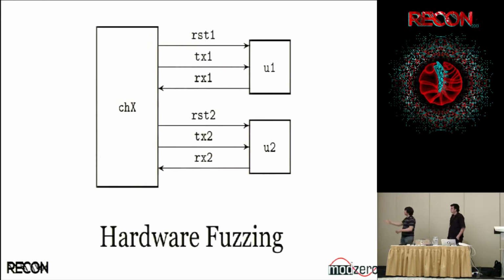So in reality, we just need a reset line and one TX line, so a TX and an RX to the device. So we could actually run 2 of these per channel. And this is the notation that we're using in our talk, this channel X. It's to show you that we have 8 RJ45s on these boards. So that means you can implement something like this 8 times on the board, or do something else, or mix and match. It's all up to you.